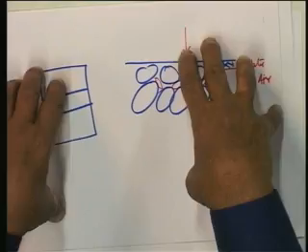Suppose a load is applied, then in a typical soil like this, actually speaking, although we are talking about the consolidation phenomenon, in reality both elastic and non-elastic components of displacements or movements will be there. The elastic components are taking place instantaneously. It is the non-elastic component which is time dependent, which is of importance to us in understanding the phenomenon of consolidation. Then what happens to the compressions?